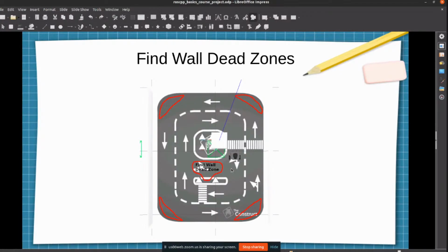If the robot is within the red zones, it'll never converge, and it'll keep on finding the wall forever and keep on spinning. So it won't find a spot where the standard deviation is, you said below? Yes. It's like way less than the minimum, because on the corners it's actually a negative corner, so it's facing away from you. And the dead zone in the middle is actually the place where on the left and right of the robot the values are almost the same. So the robot cannot decide which direction to take and keeps spinning around forever. That's really interesting.